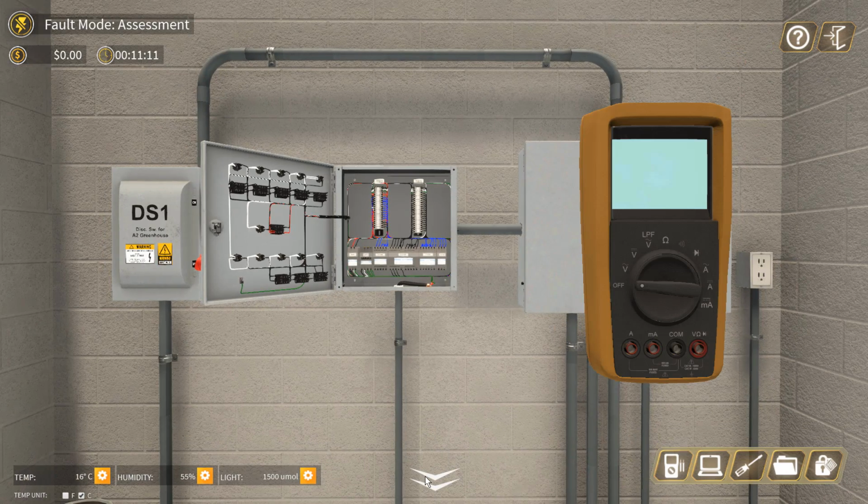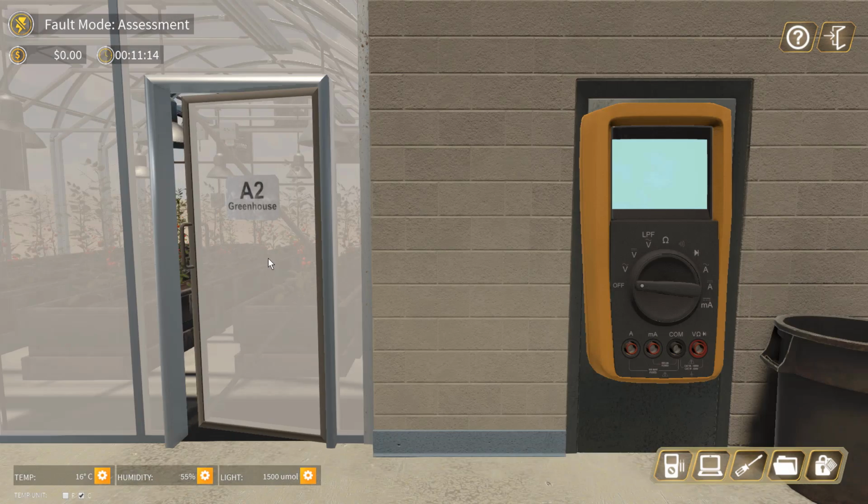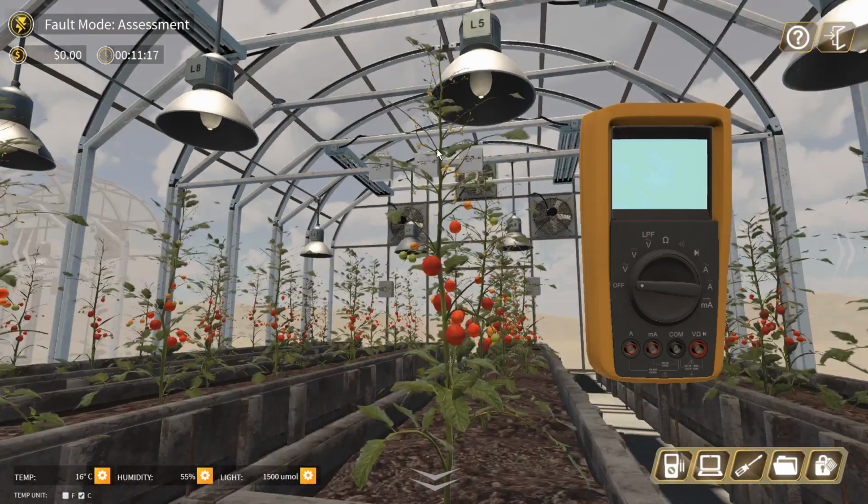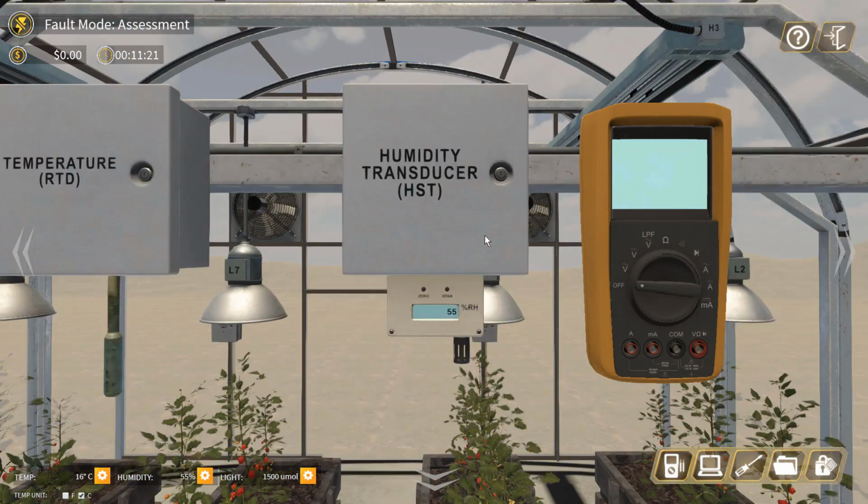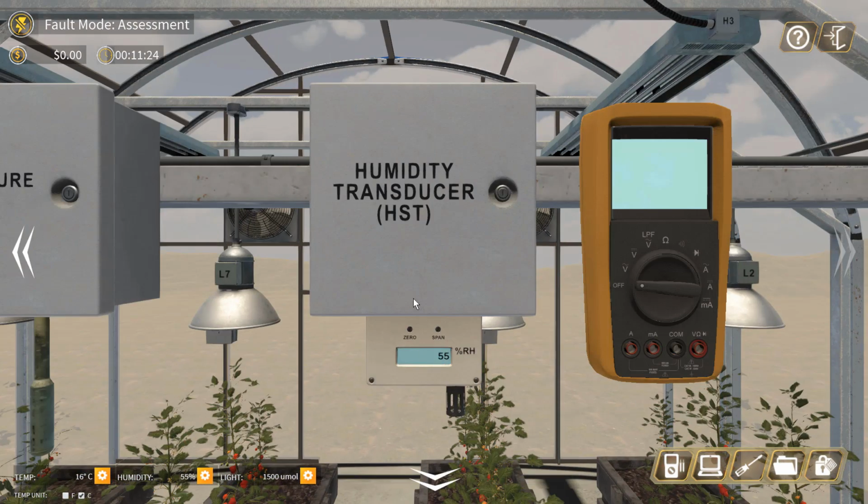and then change the humidity transducer. Okay, you see the local reading of the humidity sensor reads 55%. However, at the control panel side, it gives more than 5 volt. It should give maybe about 3.2 or 3.5 volt instead of 5.3 volt. So it means this output signal has an issue. Maybe the transducer gives the wrong output signal. Instead of about 12 point something milliampere that corresponds to about 3.2 volt, it gives you 5.3 volt.